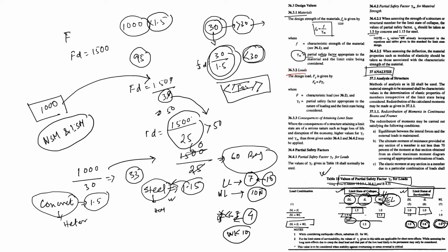So that is the load combination. So how do I find the maximum? Basically when you have various types of load, you find condition 1. Suppose using your load it comes 230, DL plus W comes say 200, and this comes 250. So you design for 250.